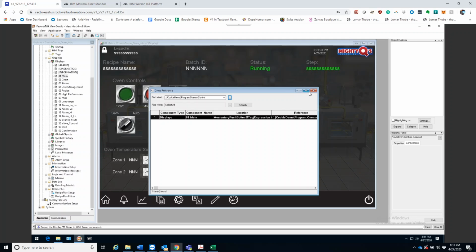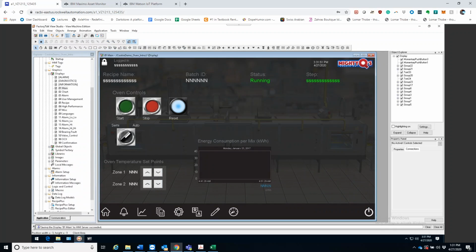So now, congratulations, you can exit out of it and you have configured communication. Basically went over how to configure communication, added a momentary push button, which is this one, added a tag to that button, and searched for application cross-reference. And you can press play to test it out. You see, it's momentary push. There you go.